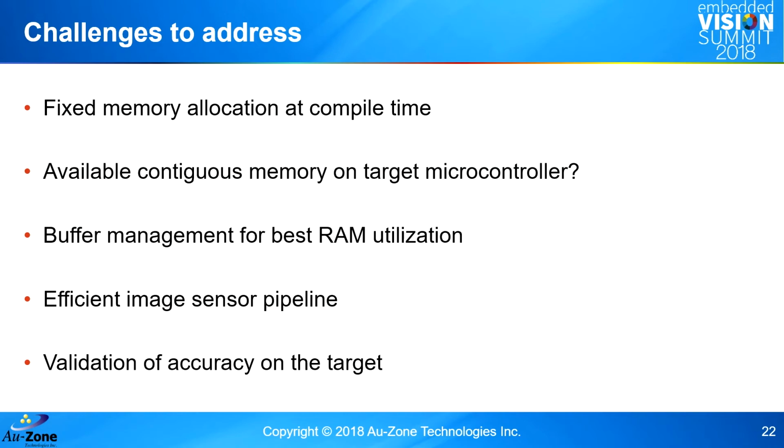It's also important that you consider buffer management. You can't have dedicated buffers for every layer in your implementation and fit it within these constrained microcontrollers. So you need to be able to know when the memory is no longer required and reuse that memory.